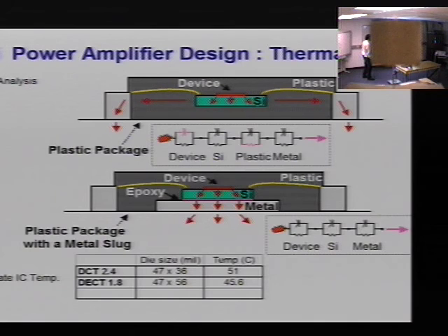Just looking at steady state, we're looking at the temperature rising to about 51 C, which is pretty reasonable, and about 45 C for both of our cordless types of designs. Like for GSM, this is also TDMA, and one really has to be very careful and understand what the heat capacity is, and do some more detailed electrical equivalent modeling, like for example an RC system, to really understand what the temperature rise and fall is for the type of TDMA signal that GSM would require.